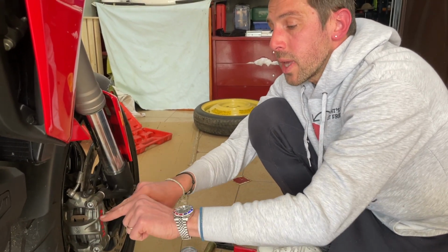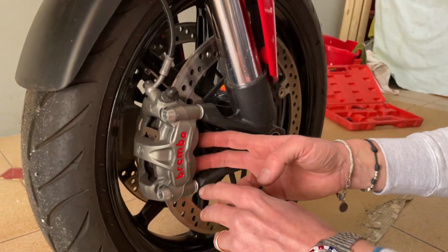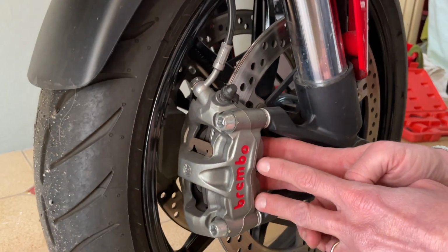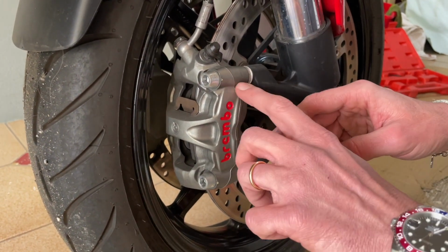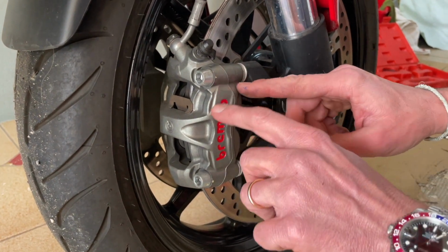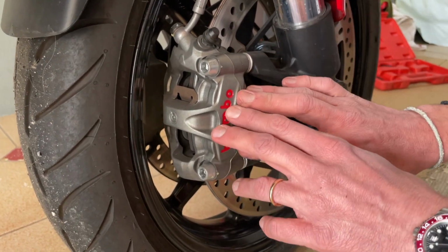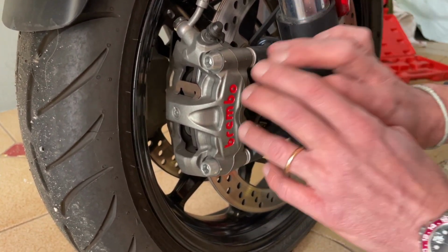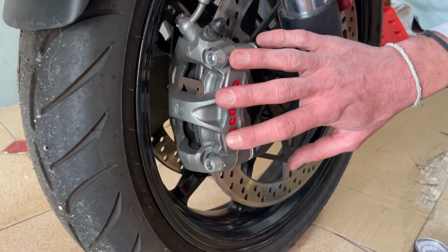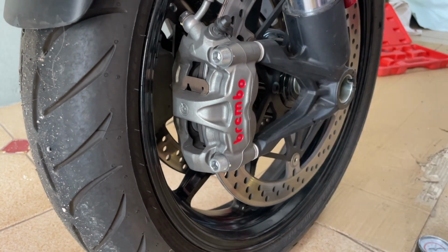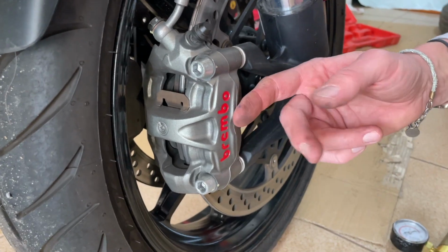As you saw, we have a reserve of oil where we have here the two pistons. So the best way is to push the pistons to the totally internal end in order to empty all these chambers, and in that way we will ensure that there will be no oil, no air in the oil circuit at all. But today we have just to make a quick fix. The bike is going to have a proper service in 1 month, so let's just bleed without dismounting the calipers.